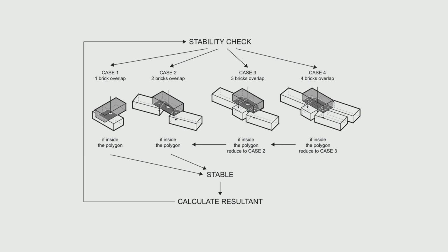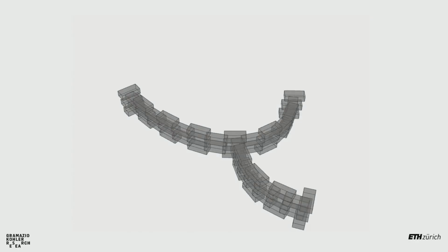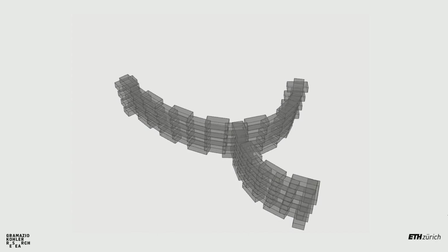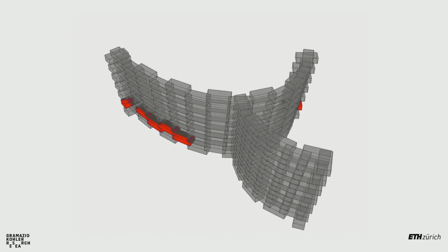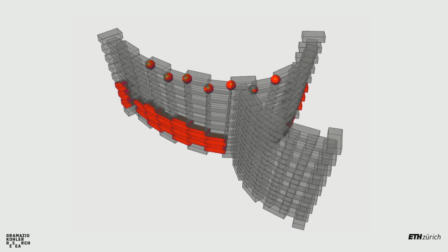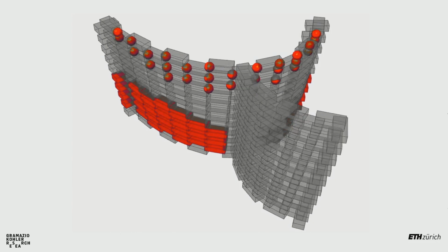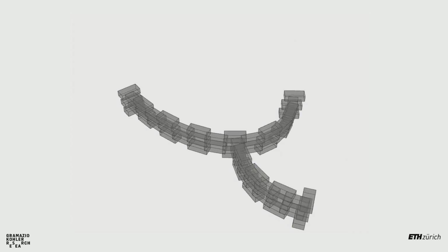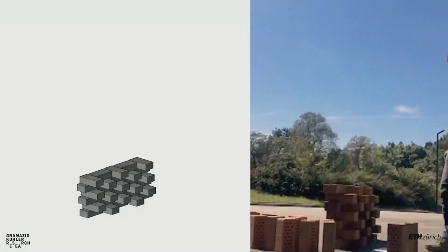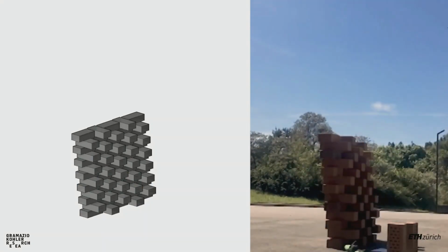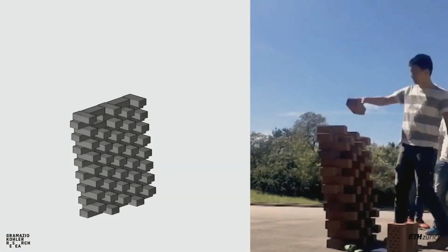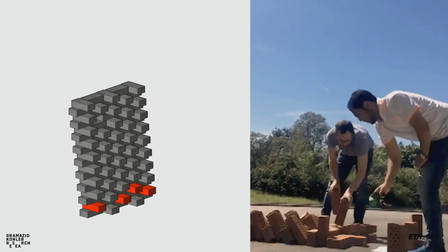We had to test every single layer of bricks that were in there. So what this allowed us to do is we could easily identify situations where the structure fails geometrically by running the simulation at every layer, and it would tell us quite reliably where it would fail. We tested it with empirical tests on single wall structures, and surprisingly, they did fall where we expected them to fall.